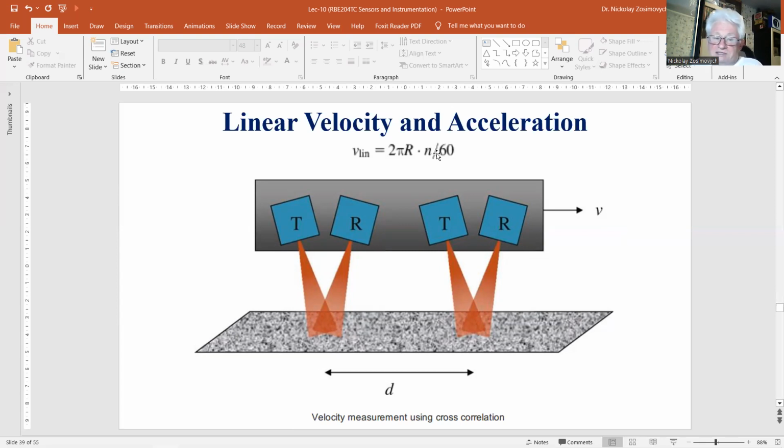Likewise, acceleration is obtained by differentiation of the velocity signal. So, in principle, any displacement sensor can be taken as a starting point of a velocity or acceleration measurement. Since any measurement signal contains noise, differentiation will increase the noise level of the velocity signal obtained in this way.